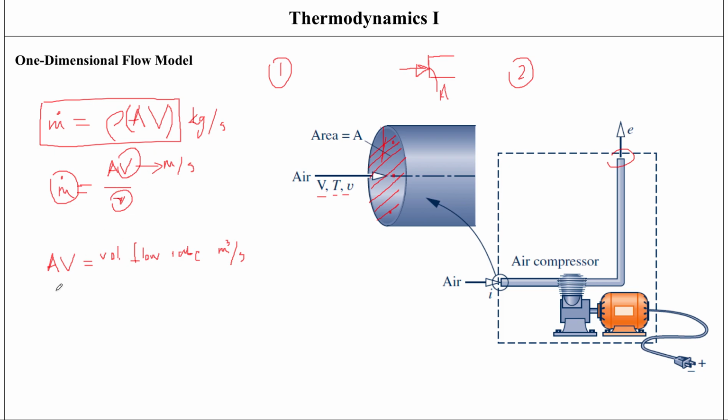So this equation represents the mass flow rate. The product A v within this equation represents the volumetric flow rate. And basically what we can do now is substitute into the equation that we saw previously, the rate of change of mass within the control volume, dm_cv divided by dt, which was equal to m dot i minus m dot e, or the summation as well.